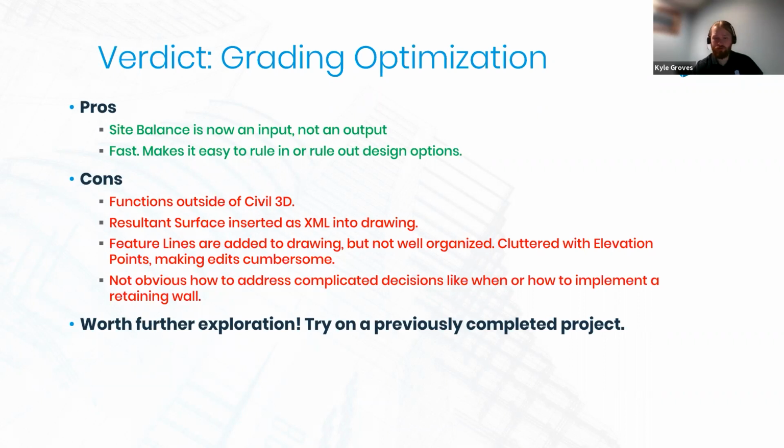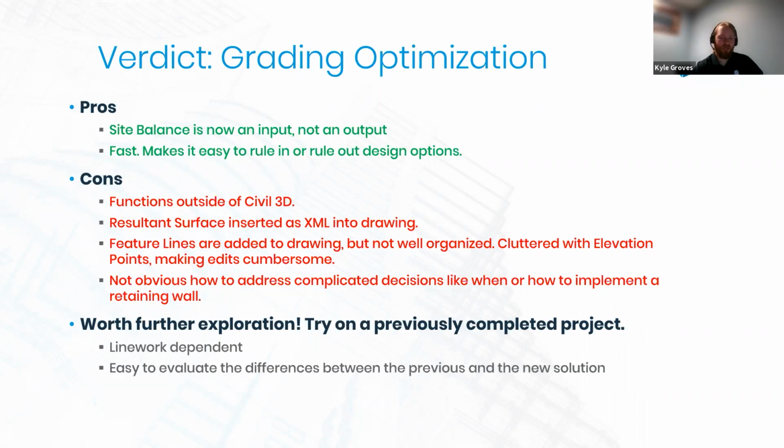I think the best way for you to determine whether or not you like this tool is to use it on a previously completed project. This tool is very line work dependent, so you're going to have that line work if you already did the project, and you'll already have a solution that you came up with. So it'll be really easy to compare those differences between what grading optimization thought your site should look like versus what you thought your site should look like.